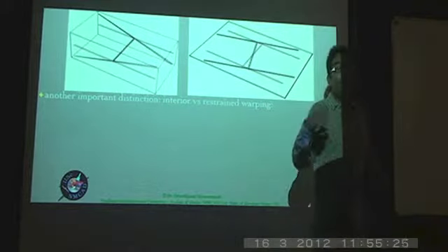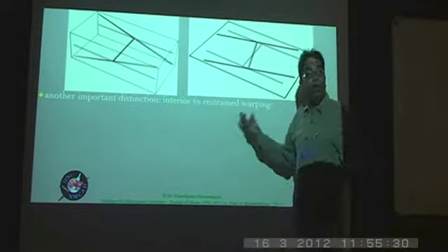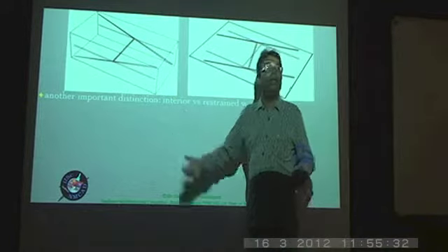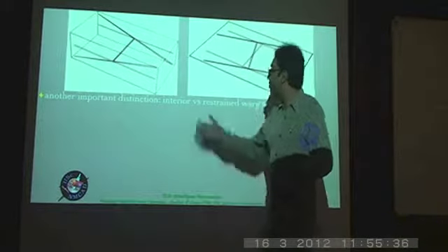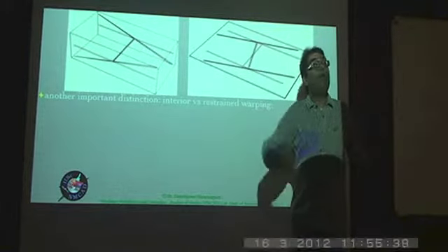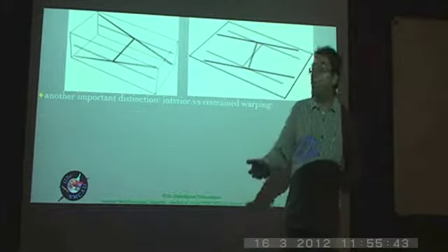The effect like the kappa 1 prime term that we have here is an example of restrained warping. The other thing that we have been talking about before is the interior warping, which is basically something which is all permeating, and is present in all kinds of beams.